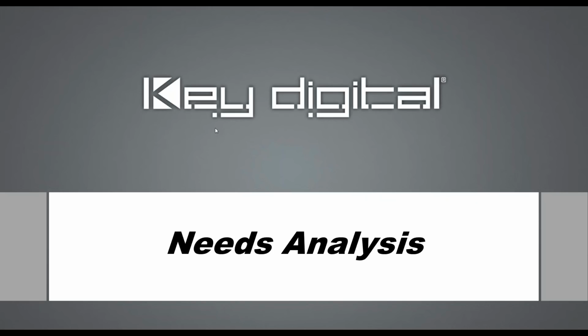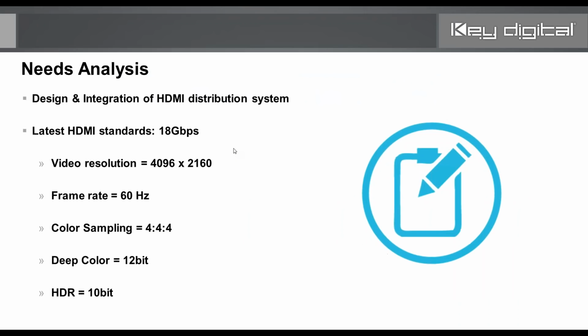So we're going to begin the webinar just by accounting for the needs of systems where we're looking at utilizing 18 gigabits per second sources into equipment, extenders, switchers, and distribution systems that may not be full 18G. And of course, this creates a problem, because if you're maxing out all of the parameters of the latest HDMI standards, your total bandwidth is going to be 18 gigabits per second.